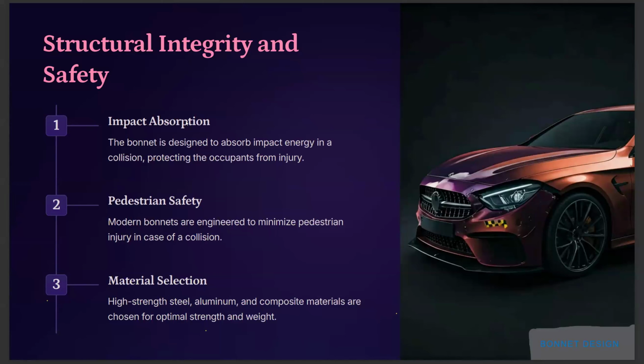When you're driving, it can be a person who might get injured just by being hit. So the bonnet has to be rigid, and at the same time a little bit flexible. If you put a hand on top of your bonnet and press it with one hand, it goes down. It feels as if it's not that sturdy. That is the engineering behind it, so that if a person or any living object hits it, the force is absorbed by the bonnet itself so that it doesn't hurt the person much.